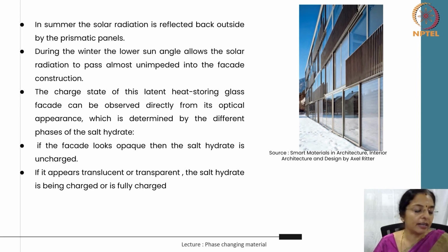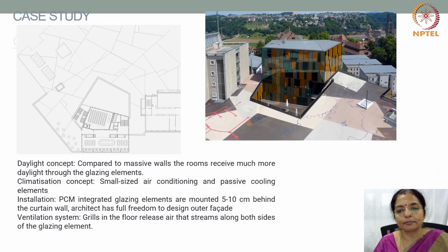The charge state of this latent heat storing glass facade can be observed directly from its optical appearance, which is determined by the different phases of the salt hydrate. If the facade looks opaque, the salt hydrate is uncharged. If it appears translucent or transparent, the salt hydrate is being charged or fully charged.